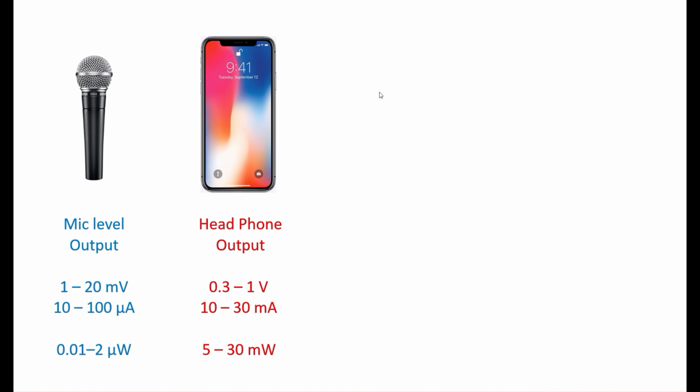And if we step it up a level and have a look at your mobile phone, you've got a headphone output, which is driving some plug-in headphones or your earbuds or whatever you're using. Once again, the numbers are super small: 0.3 to 1 volts or 10 to 30 milliamps, which is 5 to 30 milliwatts of power. Probably strong enough to drive your tiny little headphones, but not for direct connection